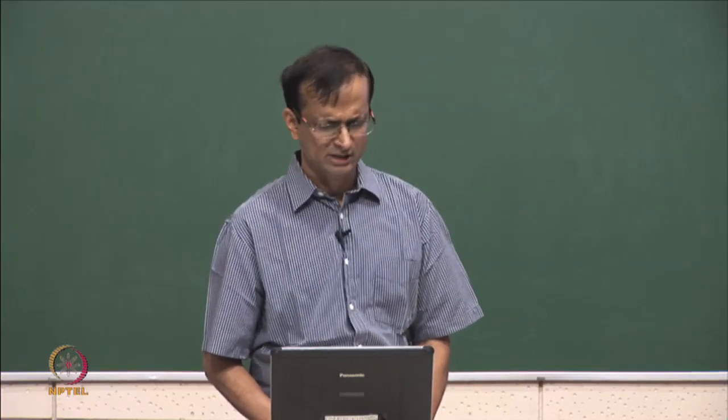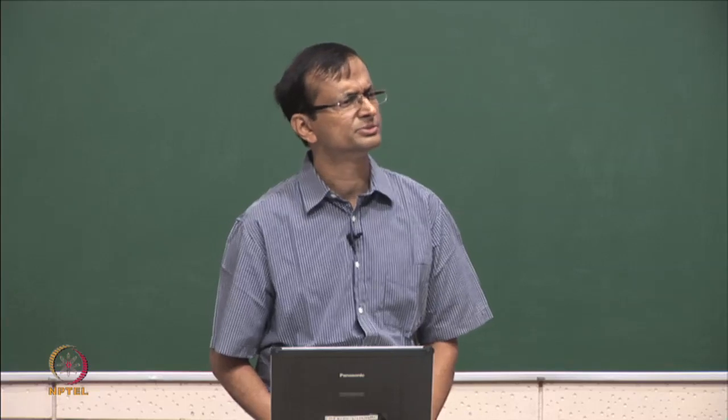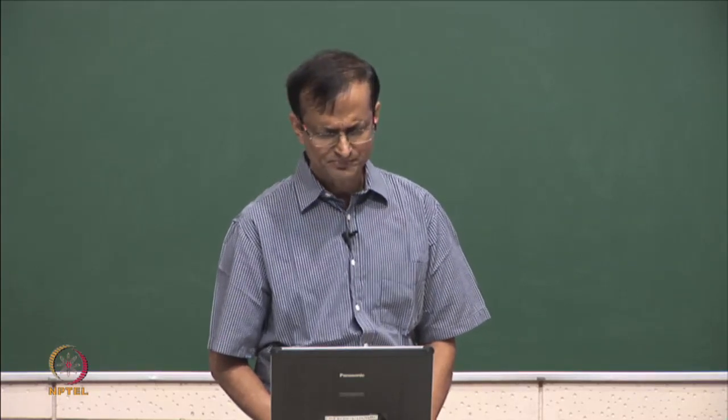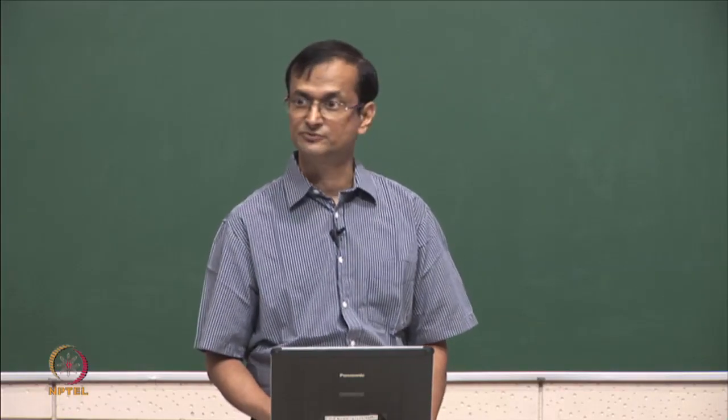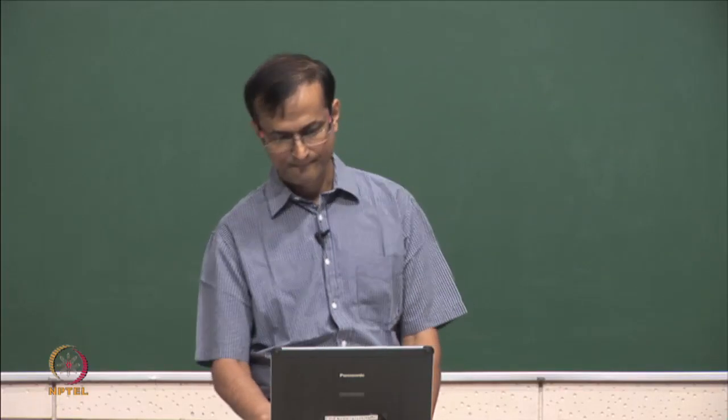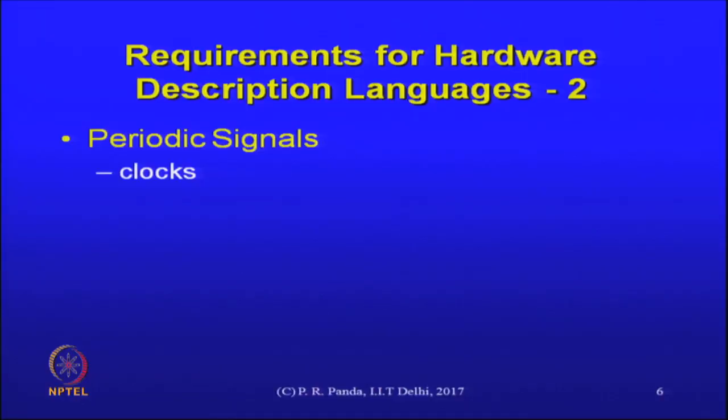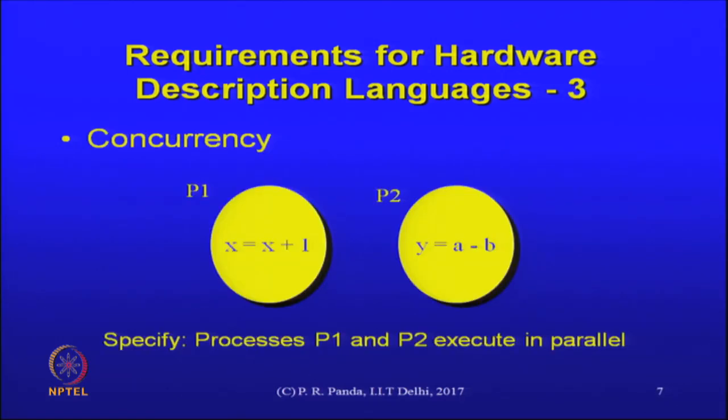So, time is essential. I should be able to create waveforms, I should be able to observe waveforms and so on. So, some mechanisms I need for specification of time and responses of the system to time. Through that, the creation of periodic signals, as we know, we need some mechanisms. Sequential hardware is described in terms of clock, and I should be able to model clocks in my design in some ways. The idea of concurrency we actually pointed out the other day.